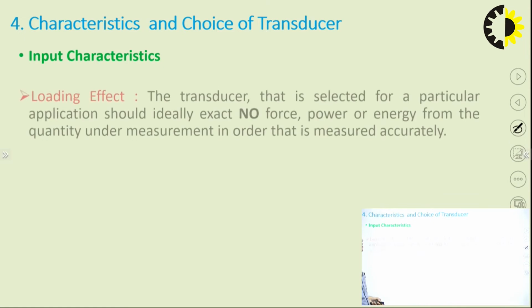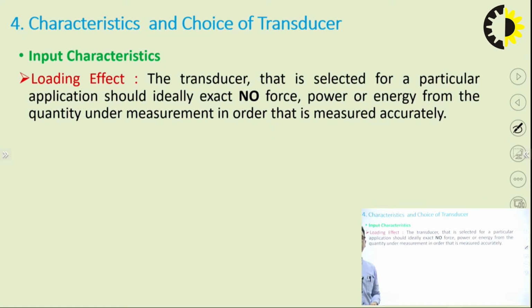And next is loading effects. The transducer selected for any application should not draw any force, power or energy from the quantity under measurement. It means that the quantity which is going to be measured should be used in measurement only.